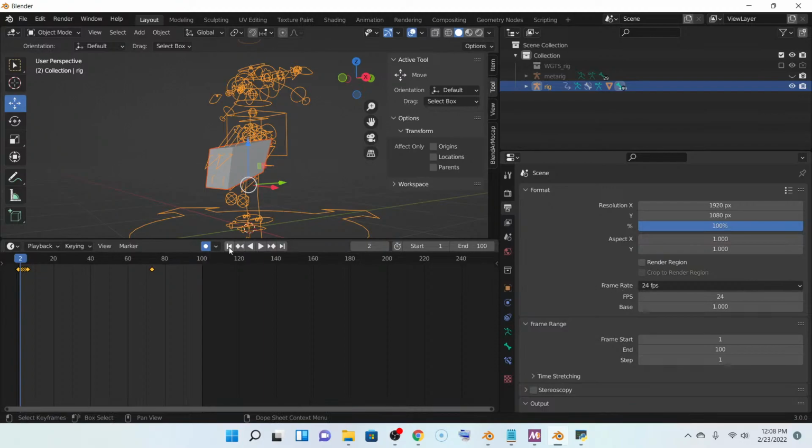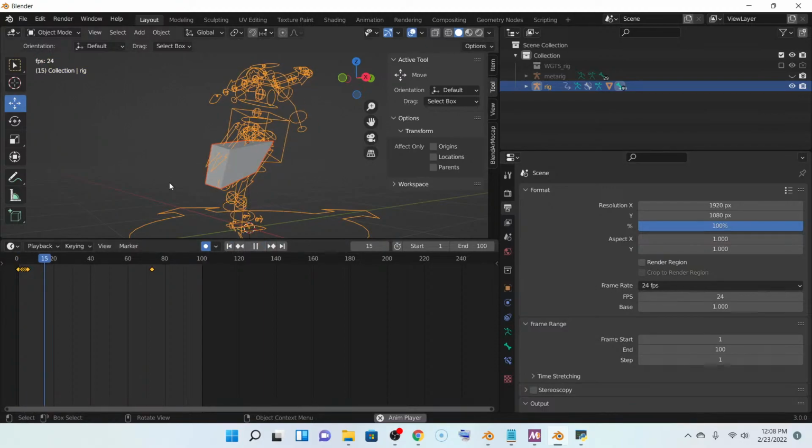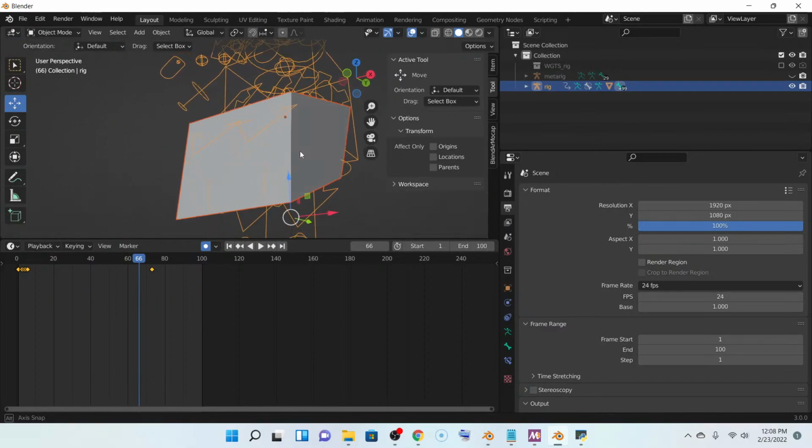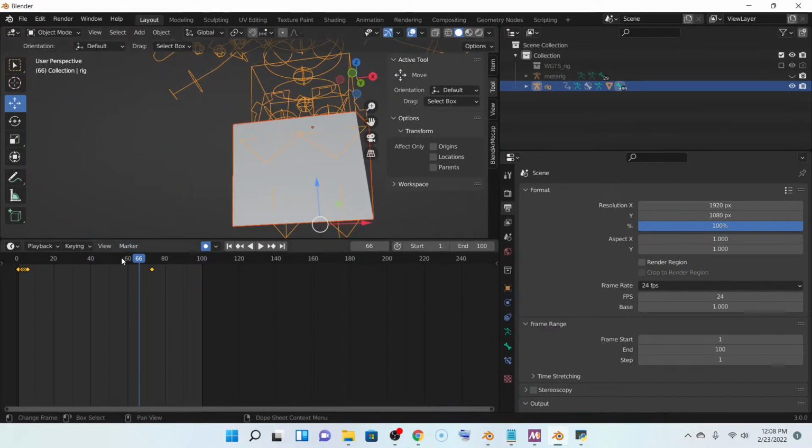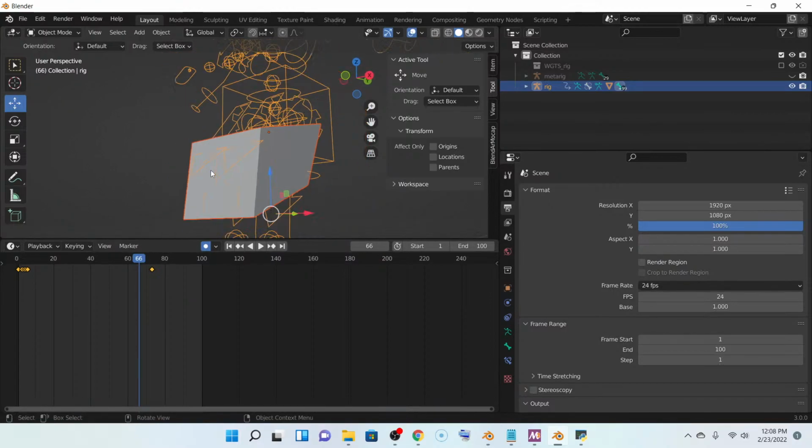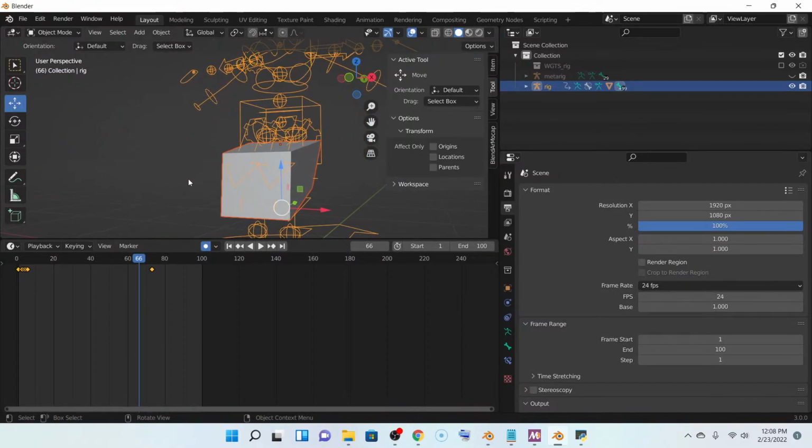Now we'll see how it's gonna move. See, so that's the move that it actually created. Pretty interesting, right? So you can do that, creating micro motions, bring down your frames, and then actually construct the animation in slow motion, but it's actually making the motions move fast or back to normal pace. It depends on where you want to put and set your keyframes.